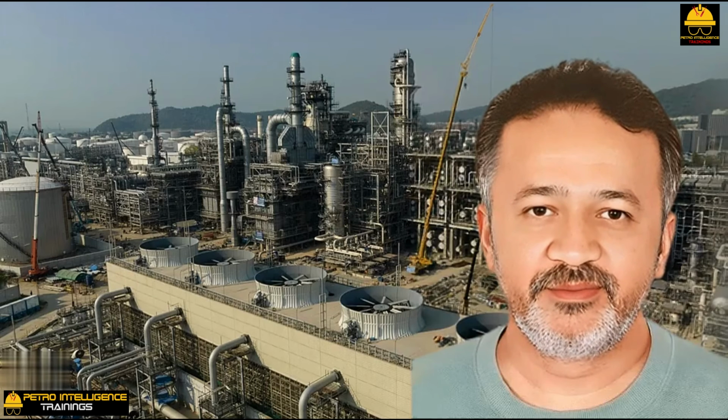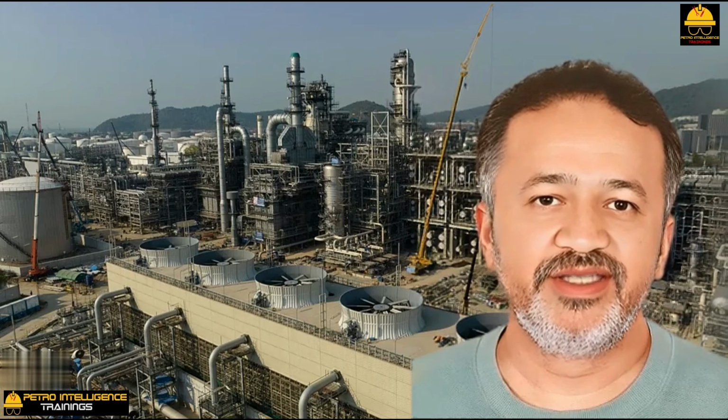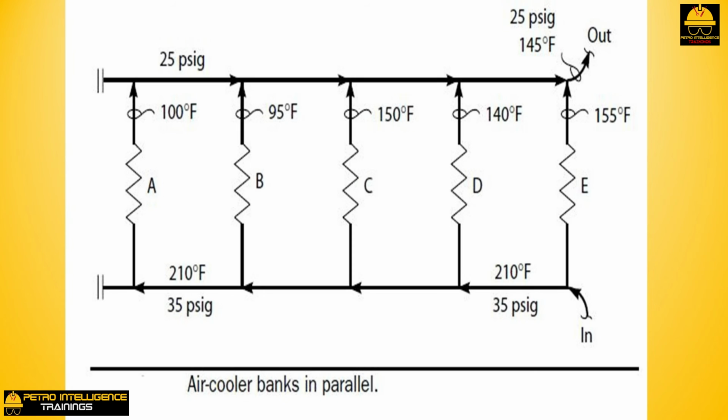Air-cooled condensers. In many process plants, the pump alleys are covered with forced draft air-cooled condensers. Dozens of coolers are arranged in parallel. I have seen services where 300 MM BTU per hour of condensation duty was easily handled by aerial cooling. All these large systems had one problem in common. They all tended to have higher flows through cooling banks connected closest to the inlet and/or outlet headers. The higher relative flows were indicated by both higher air outlet and higher process outlet temperatures. A good example of this is shown in the picture.